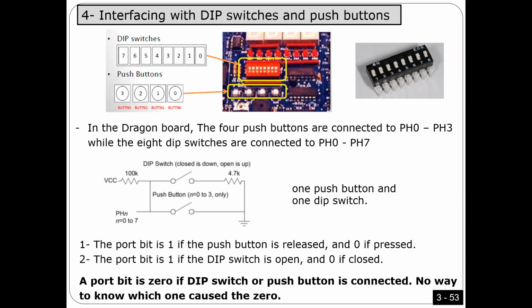Again, remember, if it is an output device, you can send data to the output device. But for input, you cannot send; you can read from the input. For example, I cannot say load accumulator A and then put here an output. It's wrong because I'm not going to read from output and put it in A. If it is an input device, yes, it's okay. You got what I'm saying?